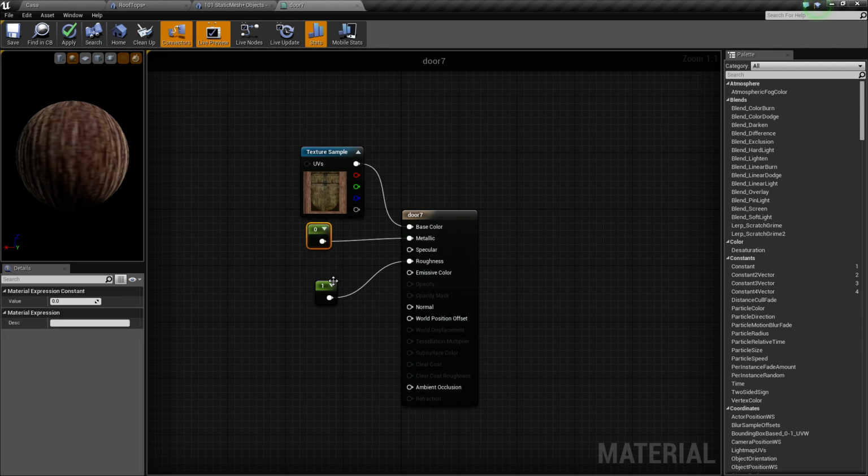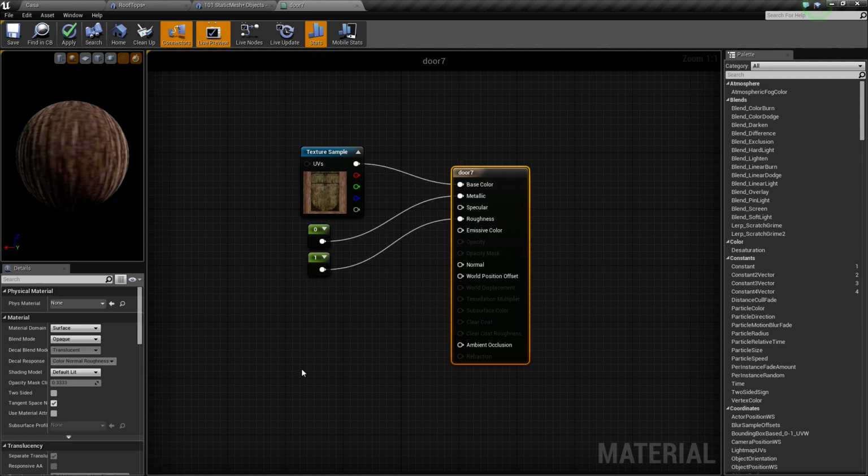This doesn't even really jibe with how materials are maintained and handled in 3ds Max, as to applying different materials and sub-shader effects to create the type of materials you want. So if you're creating a material, say for example, that is metallic, there are certain requirements in 3ds Max as to materials plus sub-materials to make that look like a metallic surface.